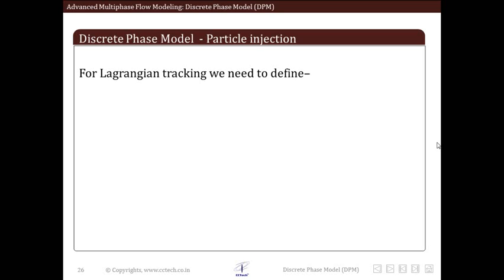In order to set their initial conditions and how they enter our domain, we have to define injections. The particles enter into the domain by way of injections. Various forms of injections can be defined which are very close to our physical real condition of the problem that we are solving, and to what exists in reality, how our instrument or equipment works.